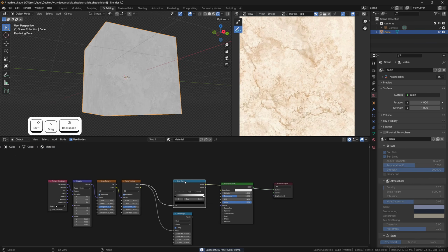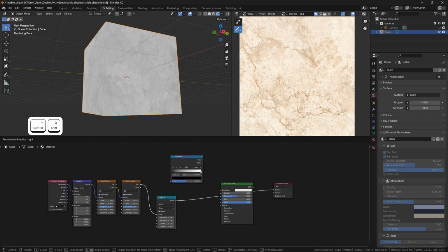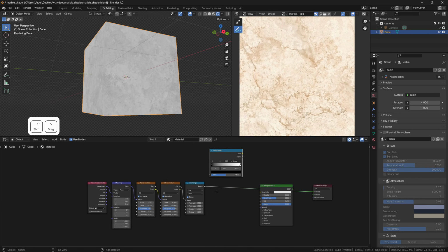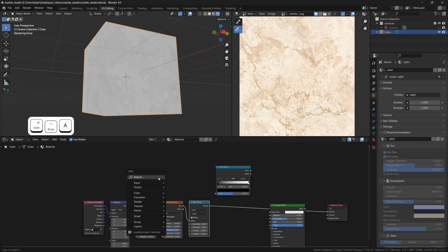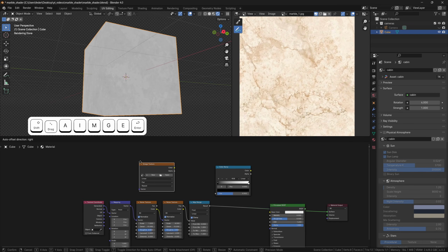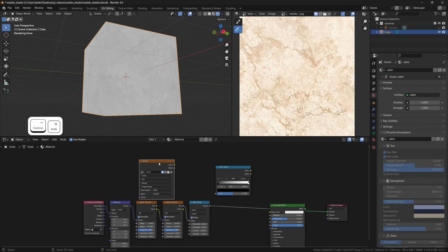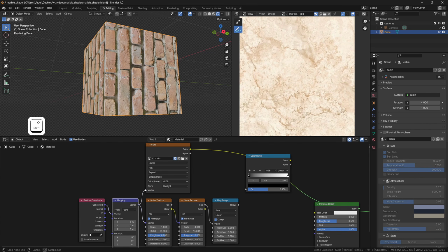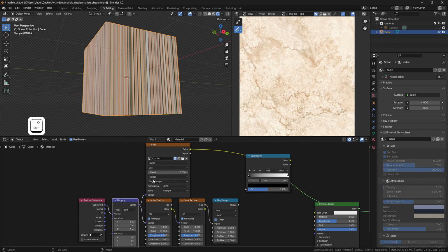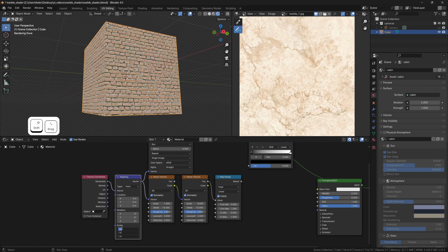At this point, I would remove the color ramp from the chain by pressing Alt and dragging the node away, and preview the map range node with Ctrl, Shift and left click, as well as reset it with the backspace key. The last step is to understand now which of the outputs of the texture coordinates node is better for our purpose. To clearly highlight the difference, especially between the generated and object texture coordinates options, I'm going to load within the shader a simple bricks texture set to box, and I'm going as well to reduce its styling a bit.